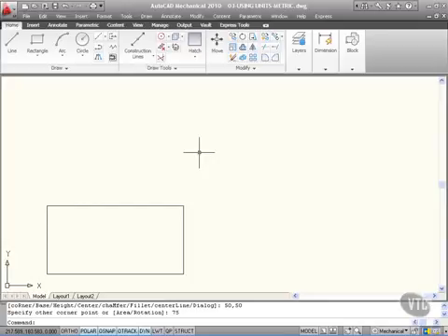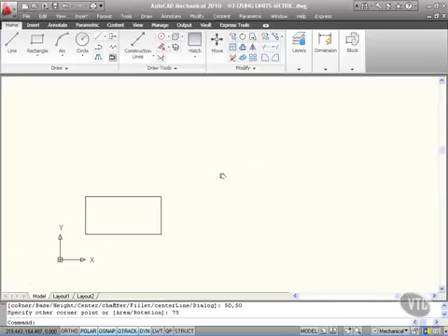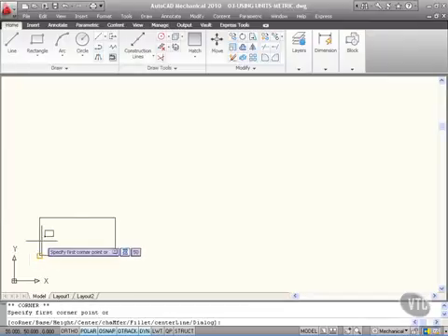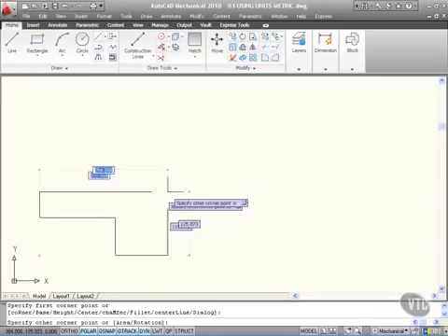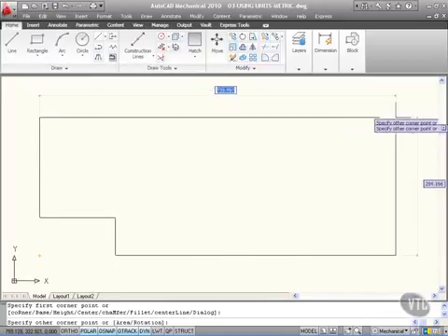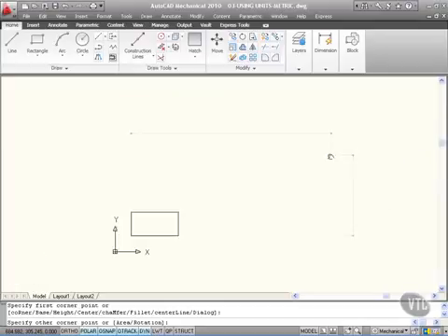Let me just zoom back a little bit, roll back on the wheel of the mouse there to make that rectangle smaller, and then hold down the wheel and pan a little bit. I'm going to go to the rectangle command again, just click on the default rectangle there. Like with the imperial units exercise, I'm going to hover over that endpoint snap and left click. As I drag outwards now, look, it just gets bigger and bigger and bigger.